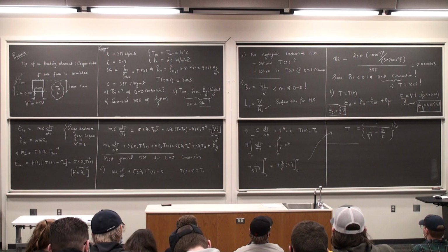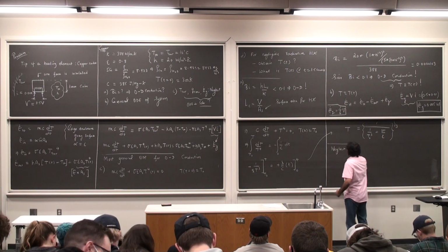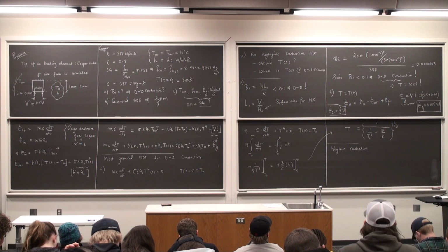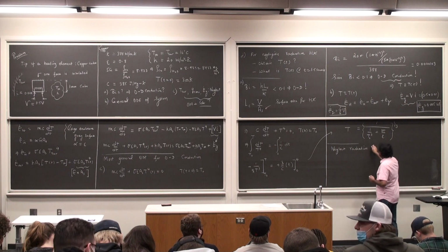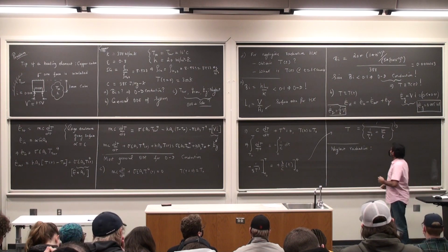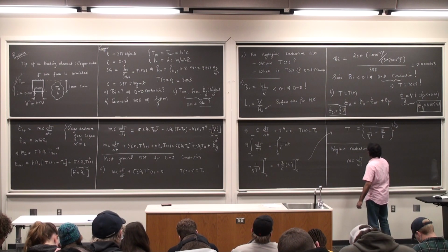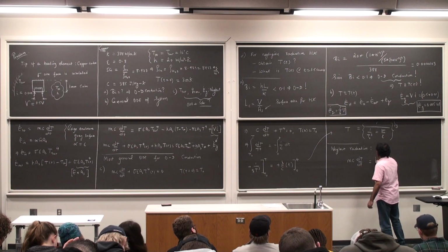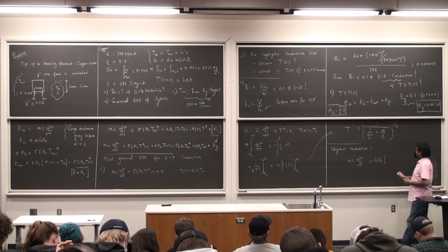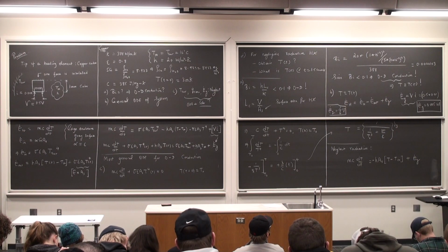Alright. Last part of the problem, which is the more important part. So neglect radiation. Which is kind of funny because we're going to spend the next 15 lectures on radiation. Okay. I have convection, I have heat generation as well. So if I write my ODE, now I end up with the following. mc dT by dt is equal to h times A suffix s, negative sign, T minus T infinity, plus E dot G.